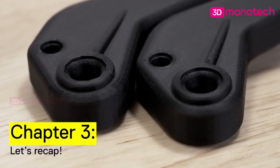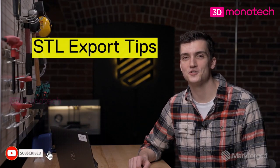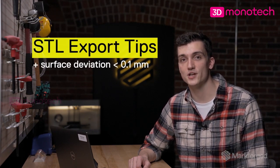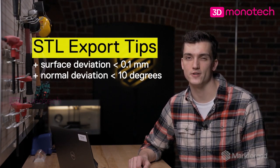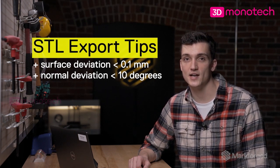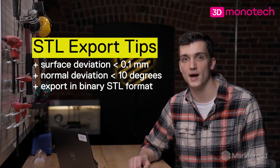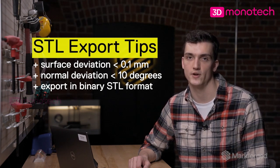All right, so let's recap. Make sure your surface deviation is no higher than 0.1 millimeters. And we suggest that you keep your normal deviation no higher than 10 degrees. If the file size is significantly larger than about 20 megabytes, ensure that you've exported in binary STL format instead of ASCII to minimize the file size without sacrificing quality. If your file size is still too large, gradually increase your surface and normal deviation until it meets your criteria.